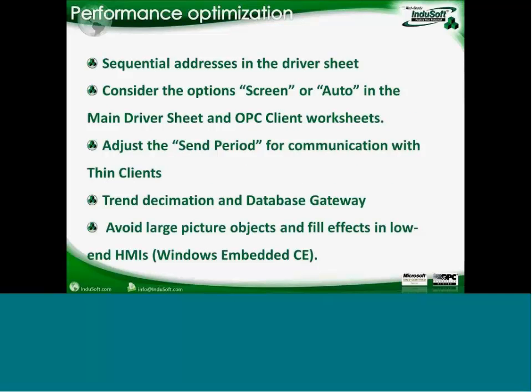Tips to optimize the performance: when you read data from PLCs that use addresses instead of tags, as much as possible, keep the communication map with the PLC in sequential addresses, so it will reduce the number of communication blocks and improve the overall communication performance.